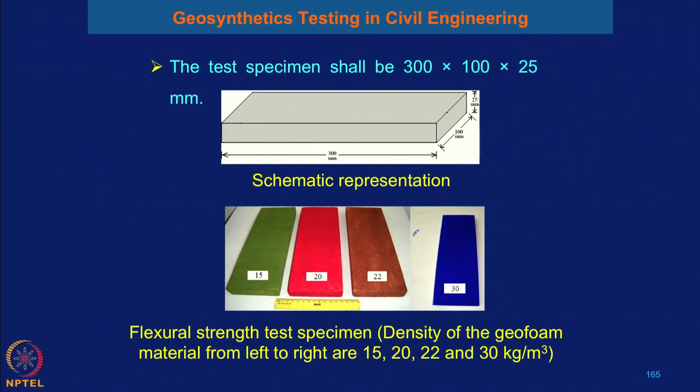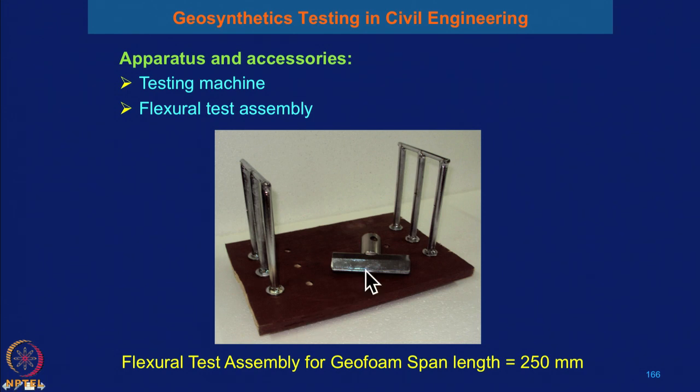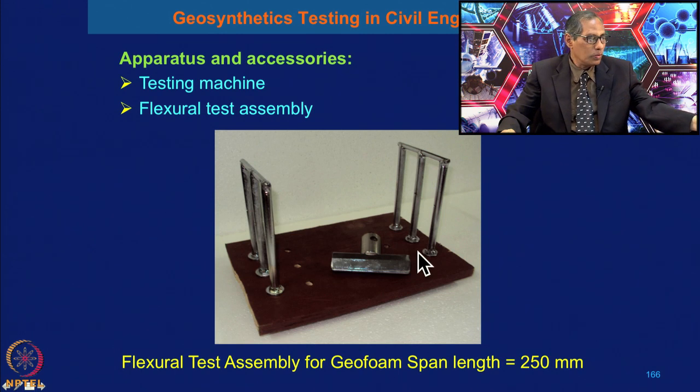So, for this test you require the apparatus and accessories. You require a testing machine, and you require the flexural test assembly. Here you can see the flexural test assembly for geofoam, with a span length of about 250 millimeter. All this equipment has been fabricated indigenously at IIT Bombay, and this test has been performed. So, this is the flexural test equipment.